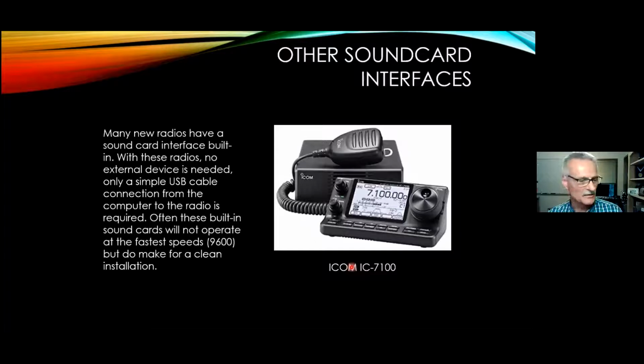Don't forget that there are many transceivers nowadays that have a sound card interface built into the transceiver. I've had questions come up from folks saying, I'm having trouble getting my SignaLink to work with my IC7100. I scratched my head for a minute and said, why are you using a SignaLink? They said, well, I want to do digital. And I said, it's already got a sound card interface in it. All you have to do is plug that USB cable in and you're good to go. And they're like, oh, why did I spend the money on a SignaLink? So keep that in mind.